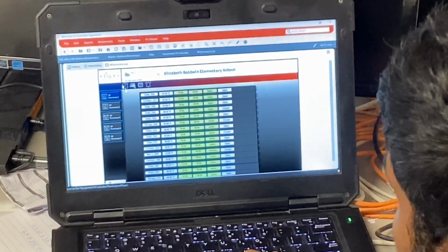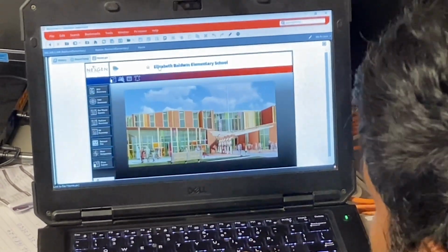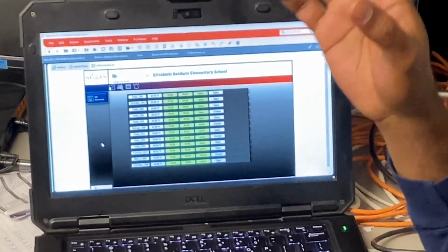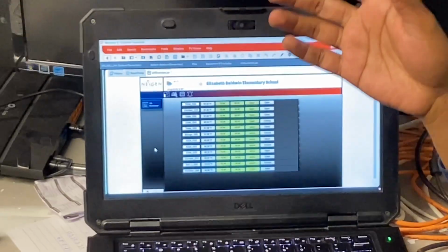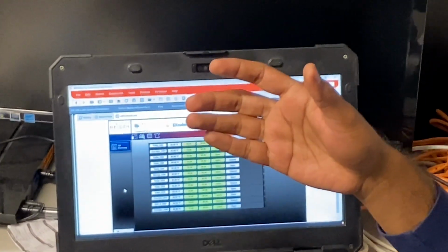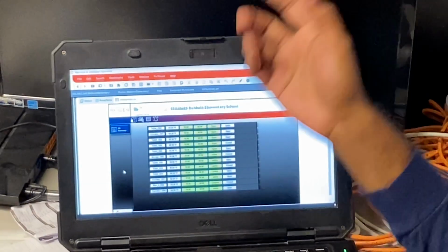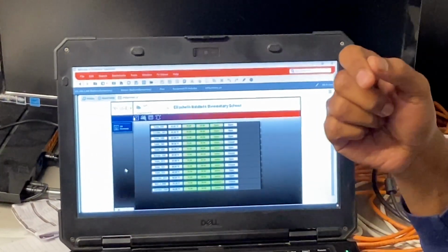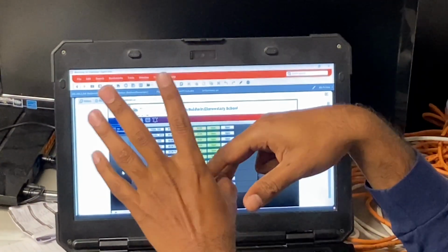And what else? Other than that, we have just the unit heaters. There are 12 unit heaters, only in the stairs, the cabinet unit heaters, with a hot water coil. Basically, they are not different from radiant panels, just they have the fan. We use the same blank plate sensor, and we give the set point from here.